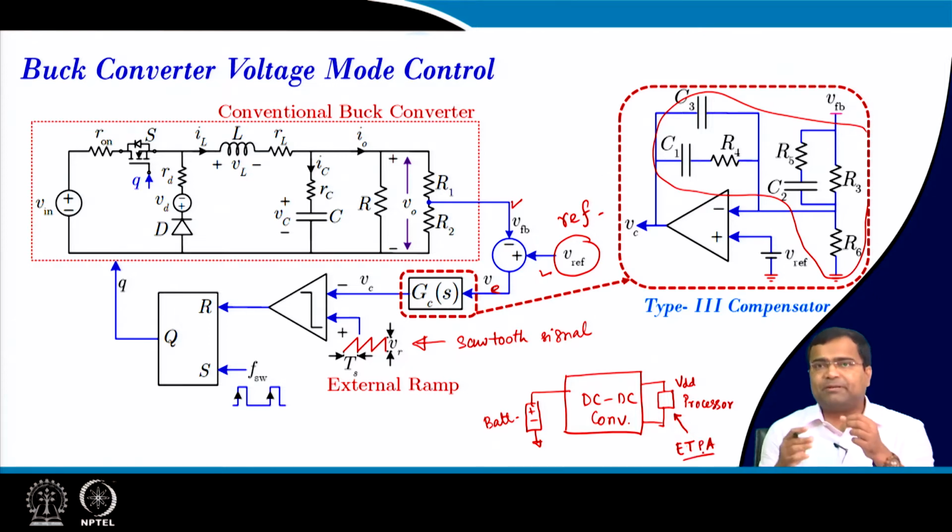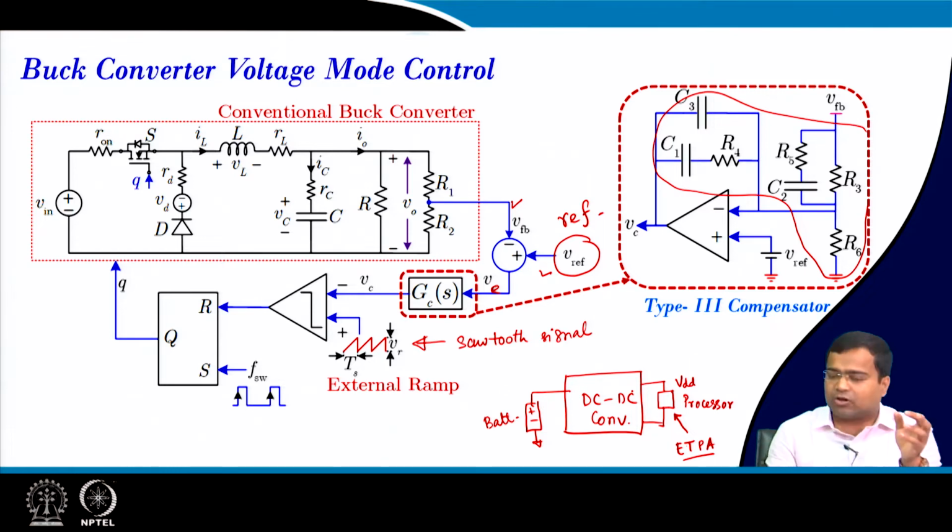because a power amplifier is used, for example, for our antenna, that means the RF transmission, the wireless signal transmission. So we need to provide sufficient power to the antenna, so the power amplifier is used, and to provide sufficient VDD we need to use a DC-DC converter, and the voltage of the DC-DC converter has to adaptively vary according to the envelope of this power amplifier, and then you need to change the reference voltage.